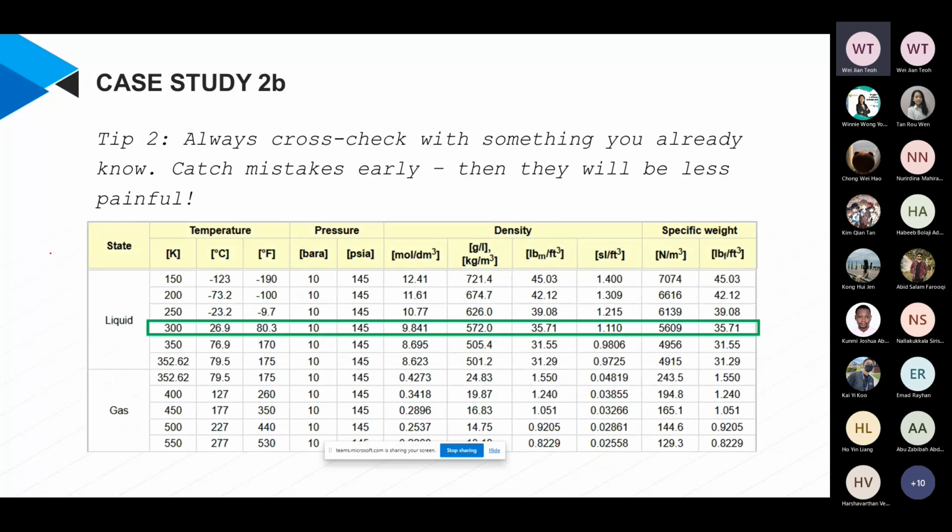And if I look closer using an engineering toolbox link, which I've shown in the chat, you can see that at normal conditions, about room temperature, at 10 bar, butane is a liquid. But above 79.5 degree, butane turns into a gas. So it now creates errors if I try to pump it. And this is sort of the common sense that we need to have when you're doing this. So in case you get some error, you don't panic. Oh, wow, what happened? Oh, it turns out that we are trying to pump a gas and you can't.